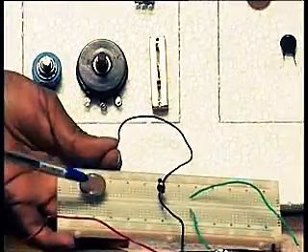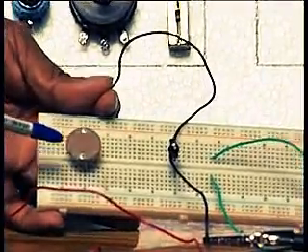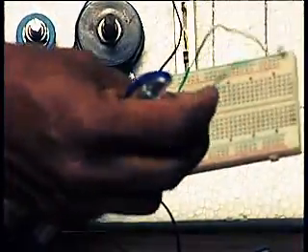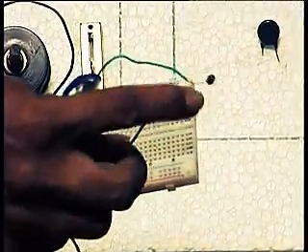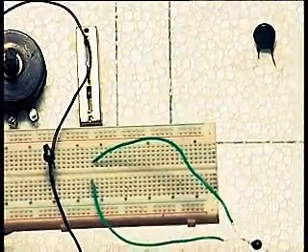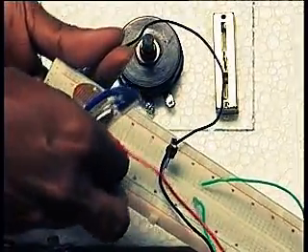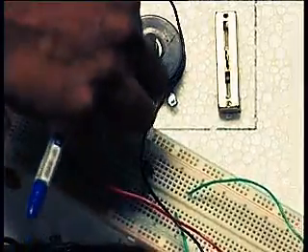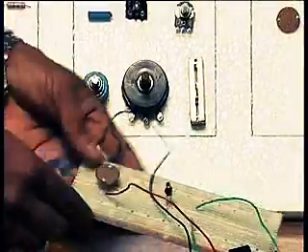Next, I am going to show you a light dependent resistor. This one is a cadmium sulfide light dependent resistor. This one is a thermistor, whose resistance value will depend on temperature. Now I am going to show you this example by connecting 2 wires. I am going to change the amount of light falling on it and measure how the resistance is changing with reference to light.